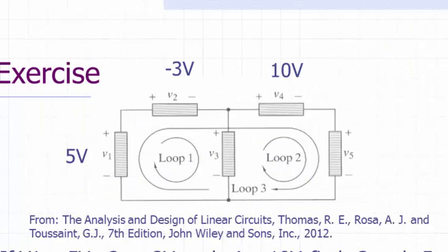In summary, when you write a KVL equation, you go through a loop. This loop, counterclockwise, clockwise, you can define any way you want. Actually, it does not matter much. And then for each component, you define the polarity by yourself. This is a reference polarity. Also does not matter. For example, like V2, the real V2 is actually here high, here low. So that's why you can see the answer of V2 is just negative 3 instead of positive 3. So your reference polarity really does not matter.